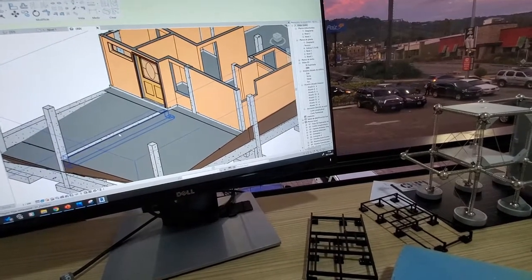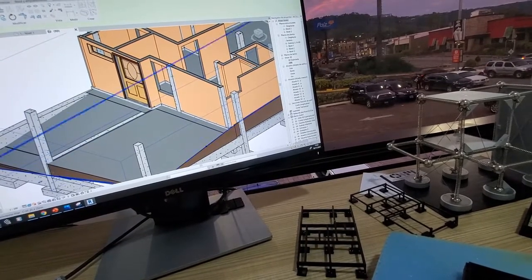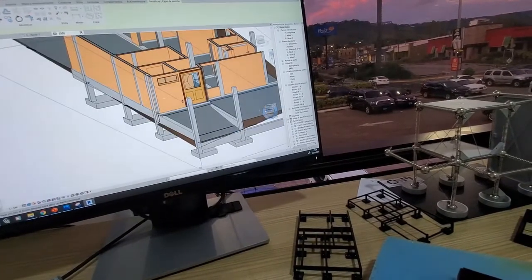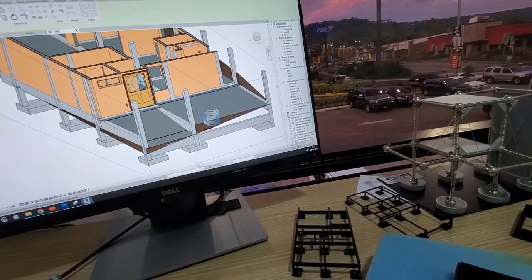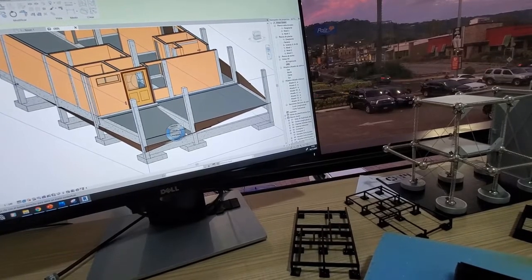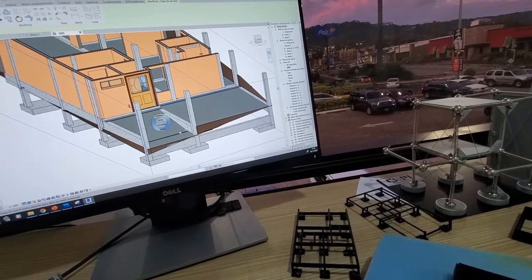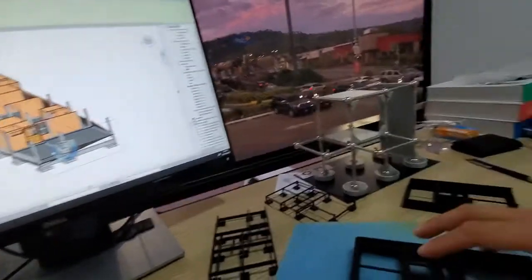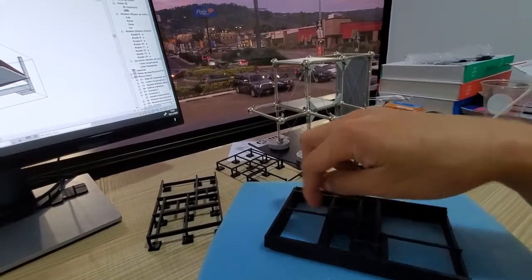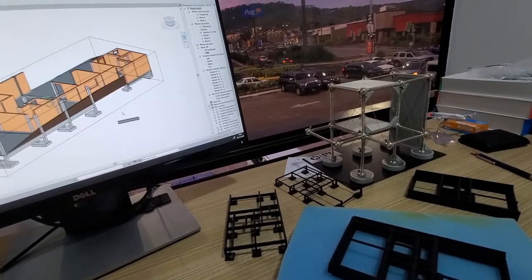Actually, this beam does not have a structural function other than transferring some stiffness to the isolated footing, and from the architectural perspective, it serves just to divide different ground levels. For example, the parking garage that should be at 0, and in this area we want to have a kind of slope, and that's the purpose of this structural system. And the same happens in the back of the house, which is this zone.